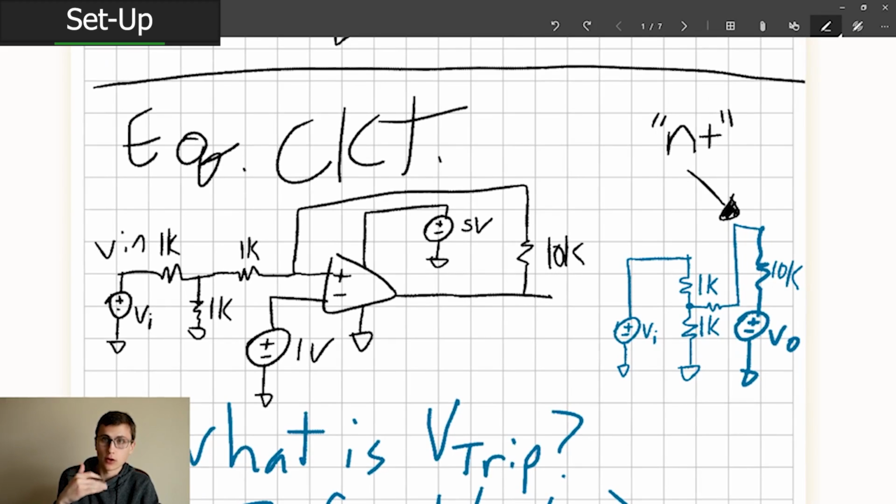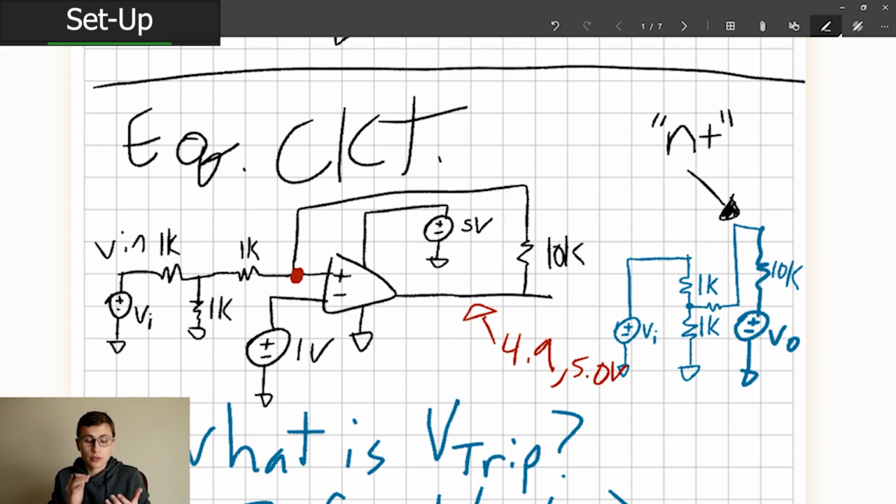So I'm basically saying that there's 100 millivolts, so the logic 0 state would be 100 millivolts, and the logic high state would be 4.9. Okay, that wouldn't be a great comparator, but that's pretty reasonable. You'd still pretty much see what you'd expect to see. You put a DMM on it, you'd see around 0 or around 5. You would understand most circuits would be able to function with that. But that'll tweak your threshold back here. Whether or not this node is 4.9 or 5.0 volts, that might matter depending on the accuracy of the threshold that you're trying to set.